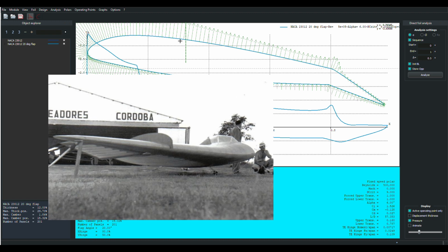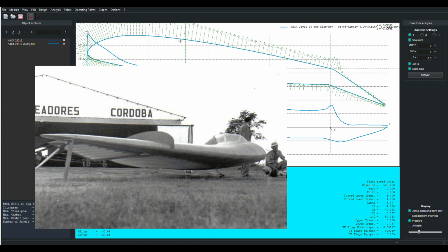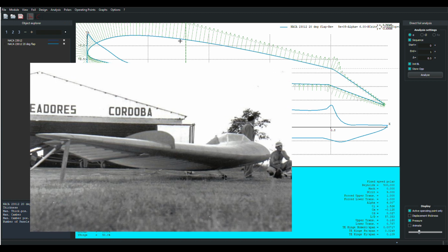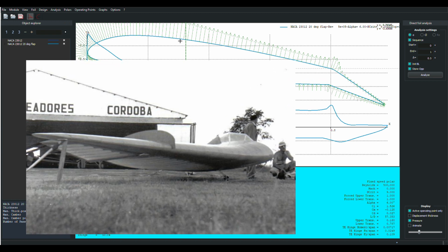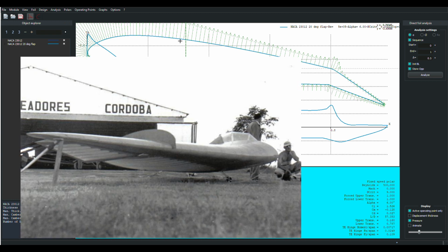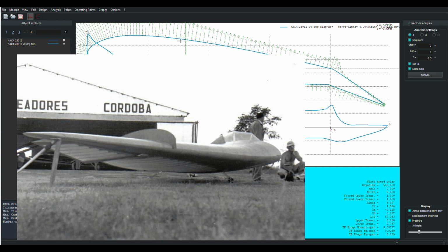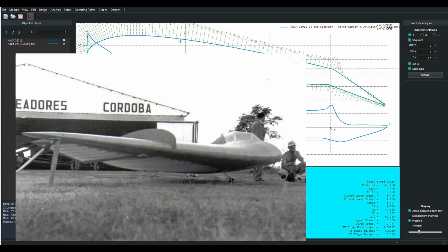So that tells me right away that they're dealing with a horrible span-wise flow problem. And they did the classic solution. They slammed on some wing fences to try to fix it. Well, this aircraft that they worked on never really flew well. And it turned out to not be foot launchable. They had to tow it. They might have had a couple of short hops, and it became a hangar queen.